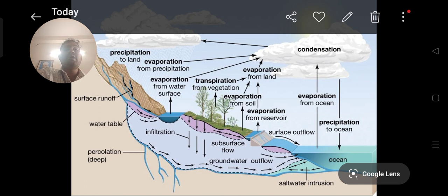Confined aquifer means the water flows between two impermeable strata. Unconfined aquifer means the water passes through a pervious medium. If an unconfined aquifer exists, a lot of water is stored at that location, and there is more probability of getting more water there. A confined aquifer has a lesser amount of water. Unconfined means unlimited, confined means limited, in terms of the amount of water.